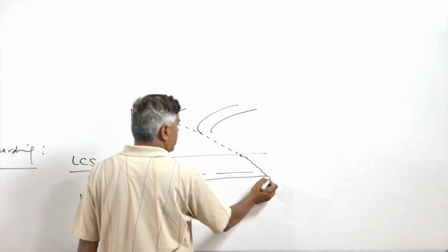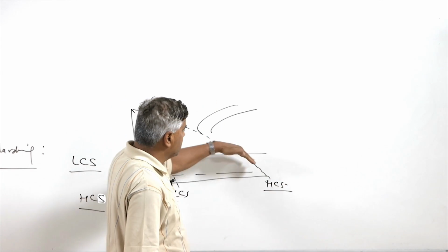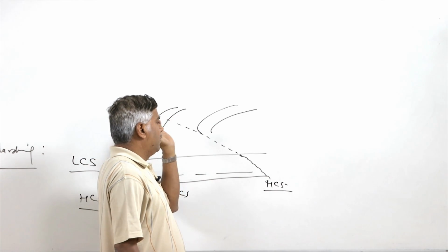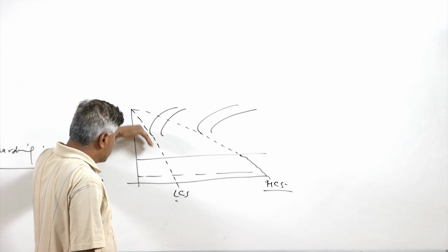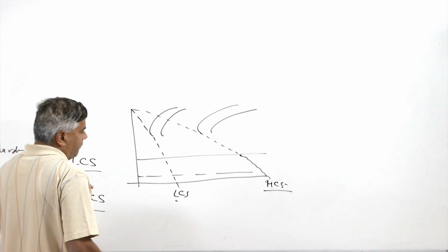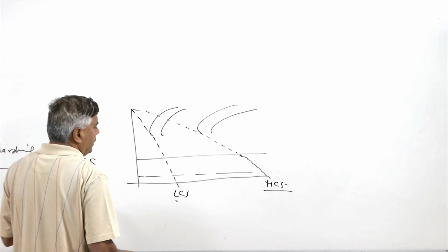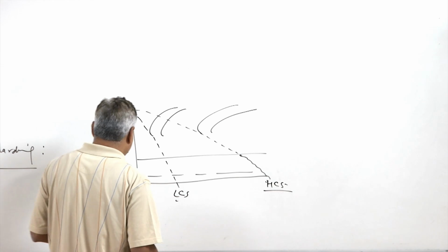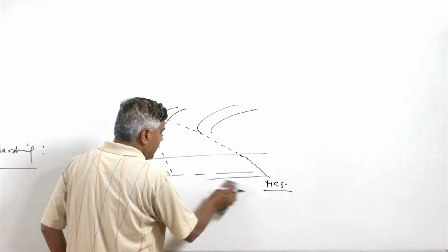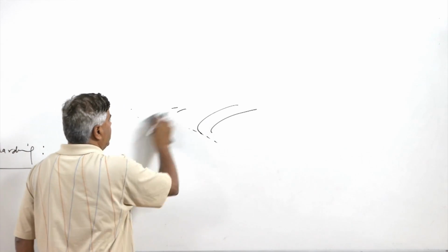So here the cooling rates for the high carbon steels are much lower. So this may be the situation where even air hardening will be sufficient for the complete martensitic transformation of the austenite into the martensite, while this is too high a cooling rate for the low carbon steel. So the fraction of the retained austenite may be more, or mostly it may have the fine pearlitic structure and a little amount of the martensite. So not much high hardness can be realized through the hardening of the low carbon steels.